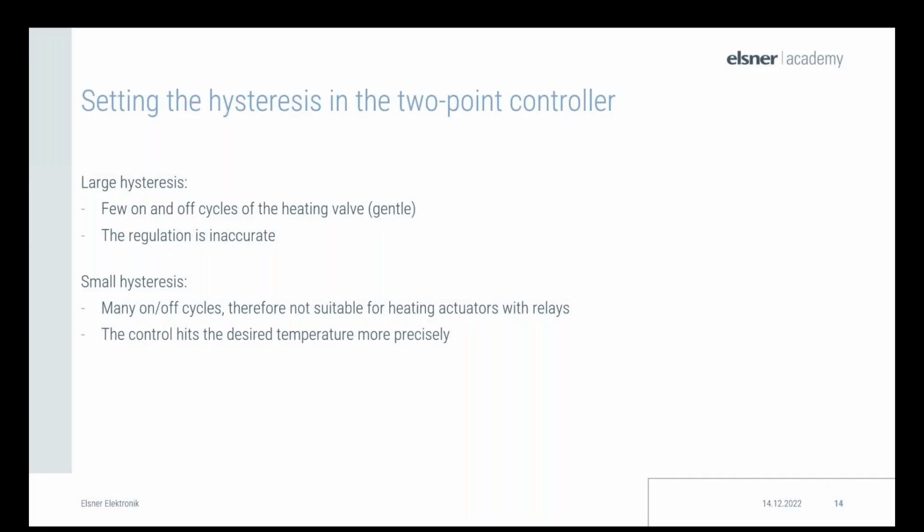Also important to note is that the valve also needs 3 to 5 minutes to open and close. Therefore, it may not work properly if the hysteresis is too small. So if they have to switch all the time, but the actual valves need 3 to 5 minutes to open, then it will not work as desired.